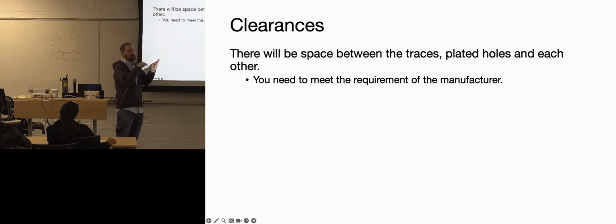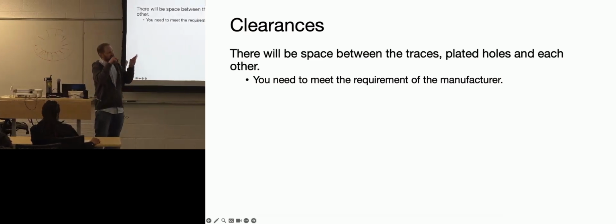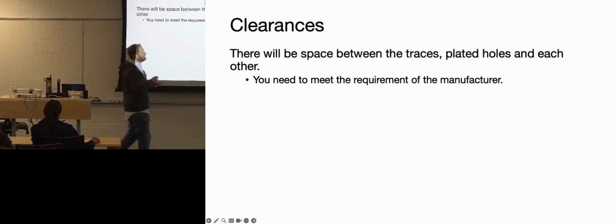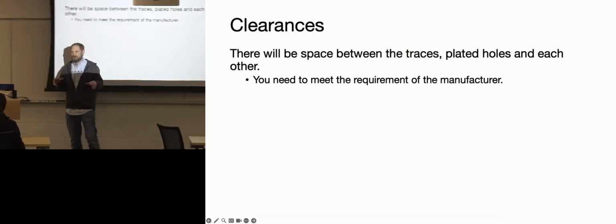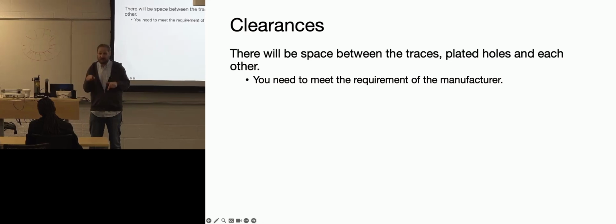And the last one is minimum hole size. So that might be 6, 6, and 8, where 8 mils is the smallest drill size that they'll allow on that PCB manufacturer. So those 3 numbers you have to keep track of. Trace thickness, clearance, and via size, what's the minimums. But whenever you guys make a PCB, the first thing you do, you figure out which vendor you're going to, and then you import their design file, or their design rules into your CAD software.